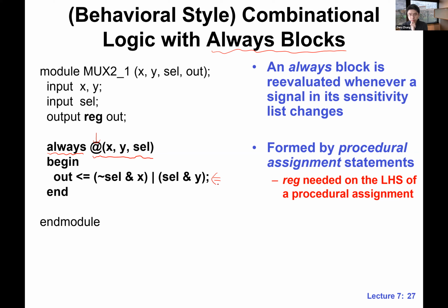Okay, so there's some question. It's great that you guys are already looking at the tutorial. So we have something called blocking assignment and non-blocking assignment. I'm going to talk about that. So Alma, you're right. If there's only a single assignment in an always block, it doesn't really matter. So in this case, we are using the so-called non-blocking assignment. It doesn't really matter much, because there's a single statement. But I'm going to talk about this.